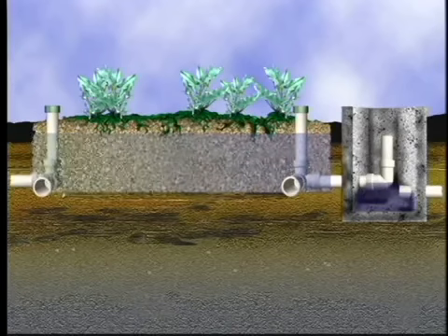Plants in the wetland must be able to survive in a saturated medium. Though both hard and soft tissue plants can be used in the system, some experts prefer hard tissue plants, believing they provide a pathway for oxygen to enter the wetland during winter months and reduce maintenance. However, many homeowners prefer colorful, flowering, soft tissue plants.